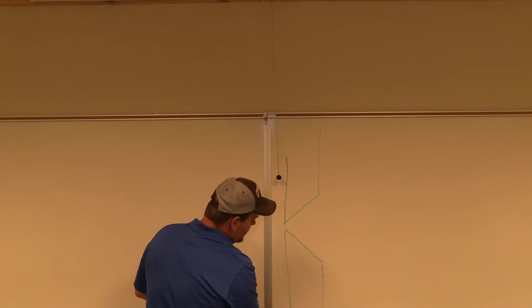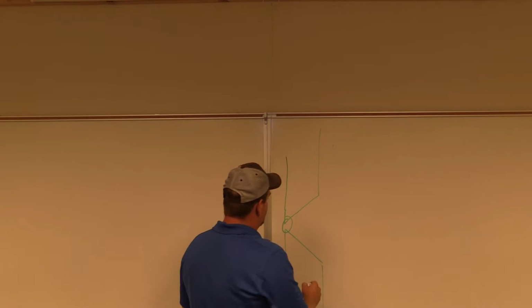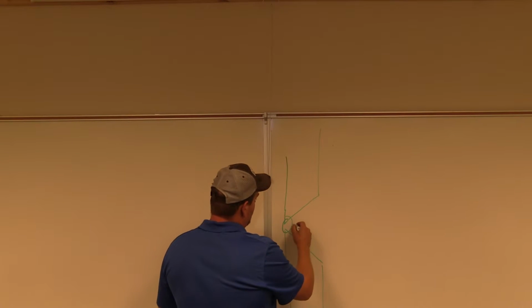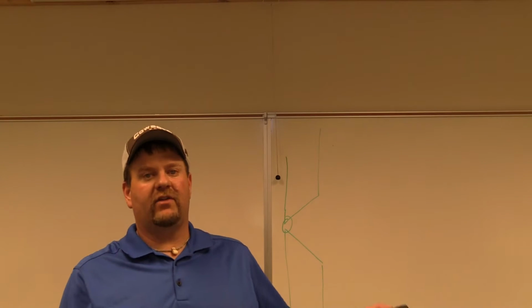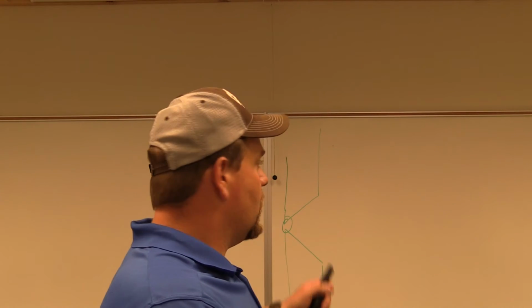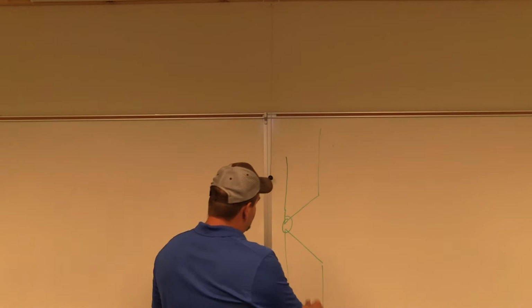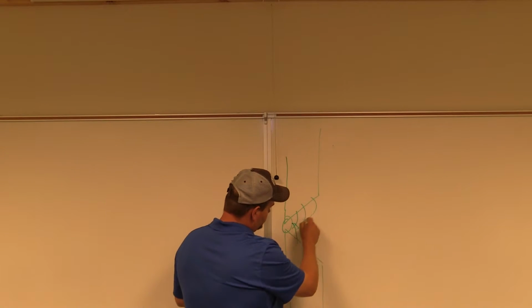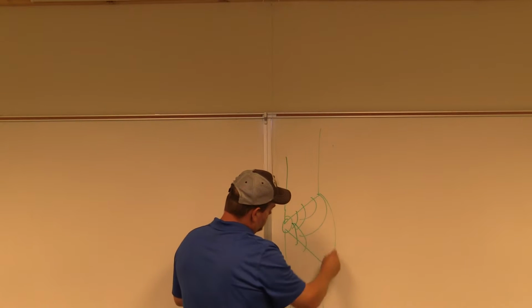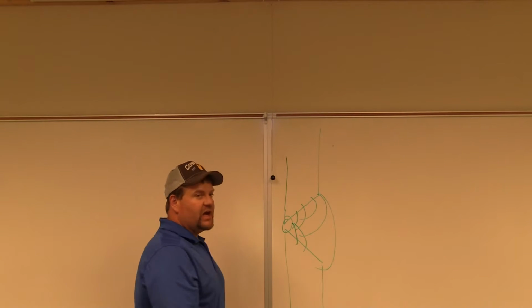So as we're gas metal arc welding this together, we put our root in, okay? And then usually what we think is, since there's no slag, we don't have to clean it. Oh, we might want to wire wheel it and that's it, okay? Well, usually what happens is we'll get here, okay, we weld it up, and then we go to bend test that.